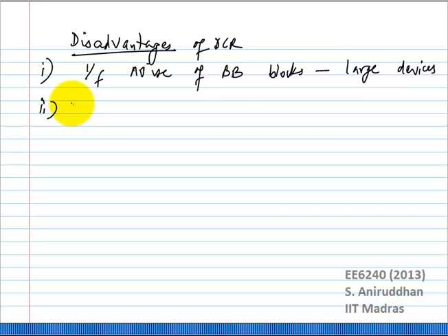DC offset, okay. So DC offset could be a problem, right? Just like 1 over F noise. Your amplifiers downstream will have input referred DC offset and they could end up limiting your performance. For example, if this DC offset was a time varying DC offset, you could actually damage part of your received signal itself.